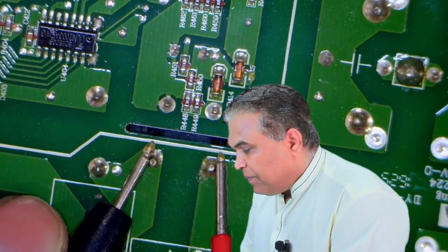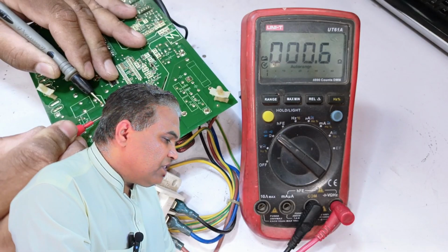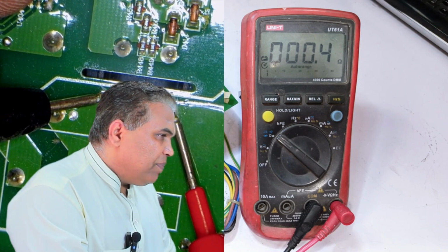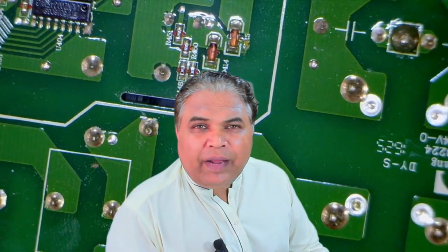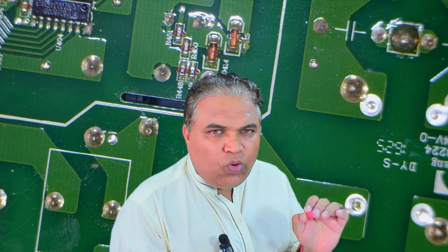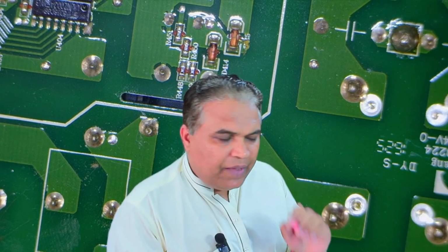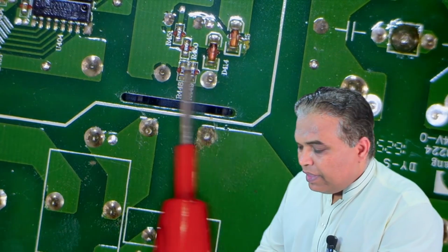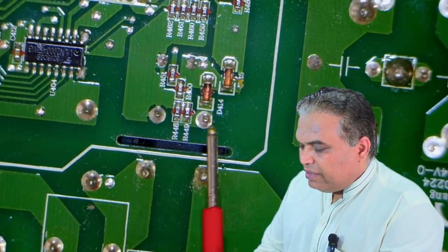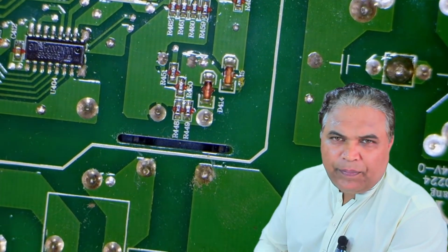The resistance value here should be very low. It is currently reading 0.4 ohms, which is absolutely correct. The first test we performed shows that thick wire passes through here. When current passes through here, a coil is present on the other side, which generates voltages in the coil. This means that a magnetic field is created inside the current transformer. Due to the magnetic field, the coil side generates very low voltages. The system uses this to estimate how much current is flowing through here.